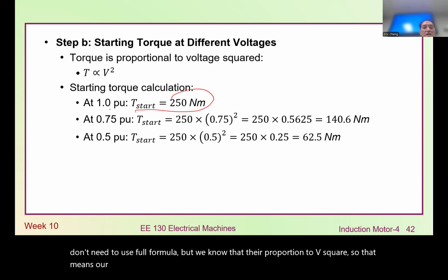And then for the motor, if you want to adjust the motor at 1600 RPM, let's see what happens. At 1600 RPM, then we can calculate the slip. So that's the calculation for slip. That will be 11.11%.